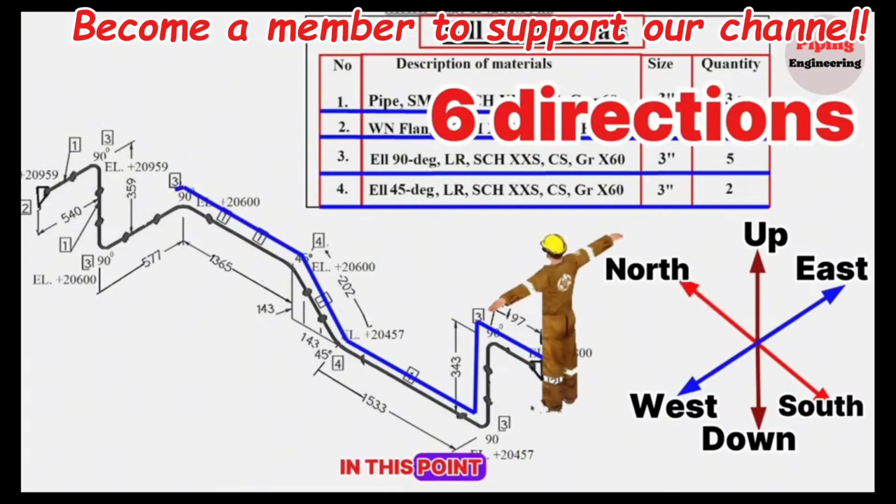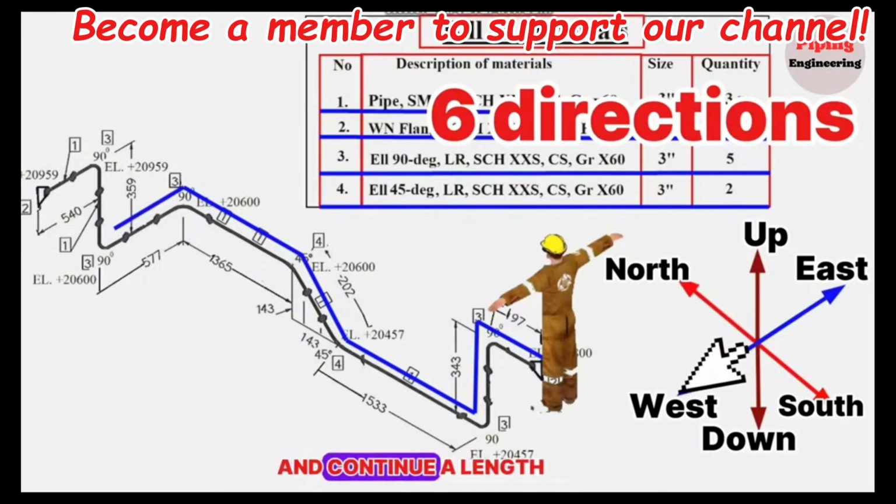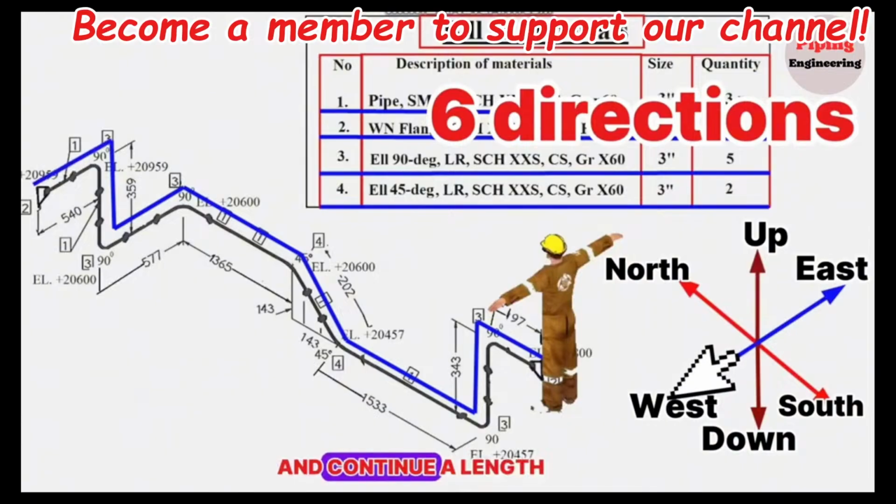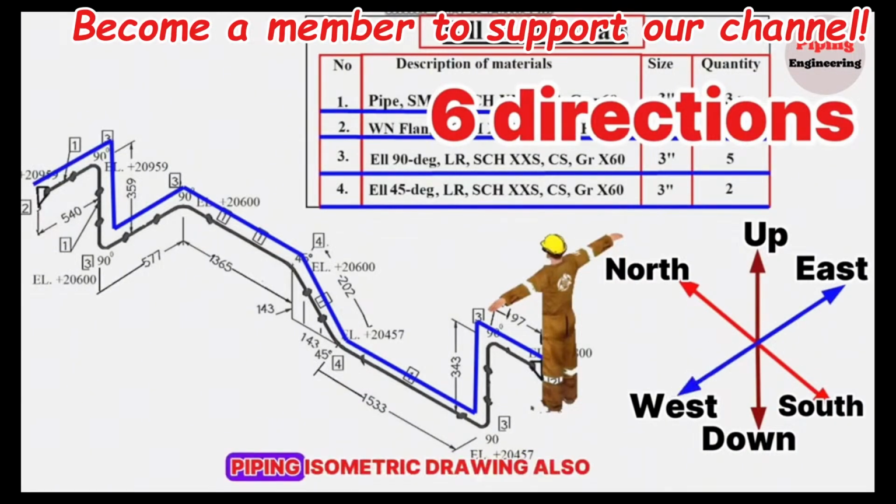At this point, the pipeline turns westwards with a 90-degree elbow and continues a length of 577 millimeters. Then the pipeline extends upwards again with a 90-degree elbow and continues a length of 359 millimeters. At last, the pipeline turns westwards again with a 90-degree elbow and continues a length of 540 millimeters. And reading the piping isometric drawing is also successfully completed.